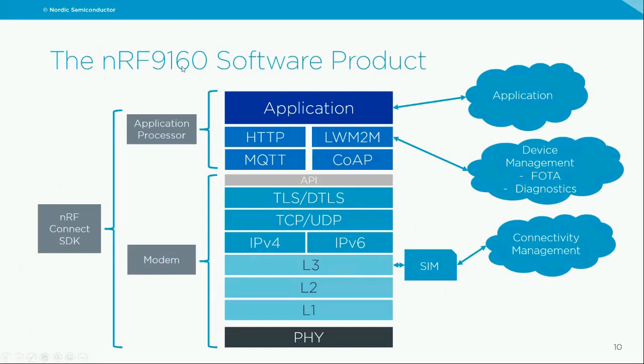So all the software that Nordic offer resides in what we call the nRF Connect SDK. And this software development kit has two key parts. It's the modem software. The modem software is a binary that is delivered as closed source from Nordic. This is mainly due to the fact that we need to certify our SIP both regulatory and for carriers or mobile operators. And that certification will be broken if you start to change something on the lower layers here. The other thing is that all these layers up to TLS and DTLS is very standardized. You will need all of this for almost any connected applications.